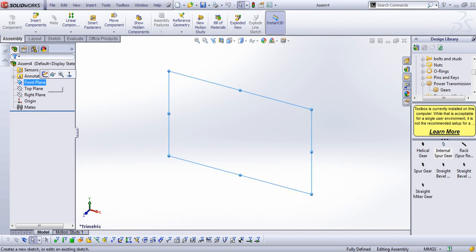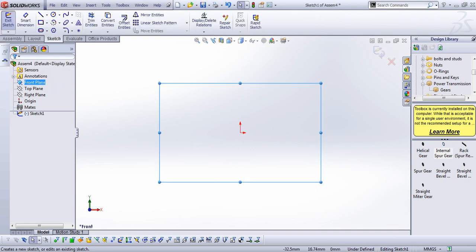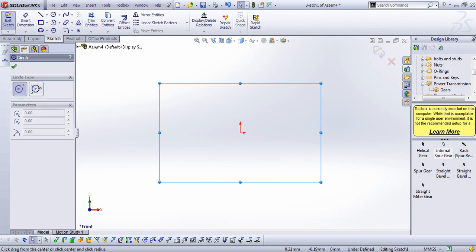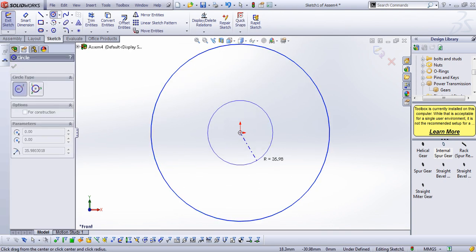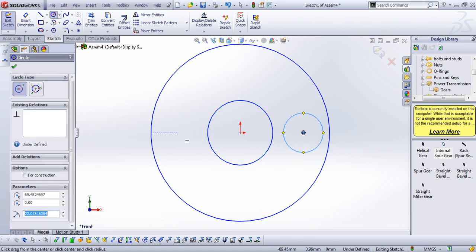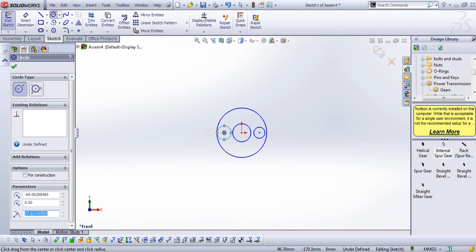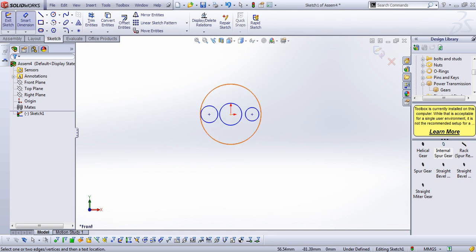I make a few circles and then start to bringing parts. So we make one large circle with the diameter of 200, one with diameter of 100, and then here one with diameter of 50, 150 here, and then all the way down we go and we make one here with diameter of 50. Let's just add the dimensions here as I mentioned.